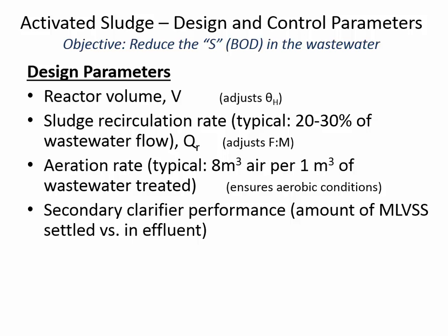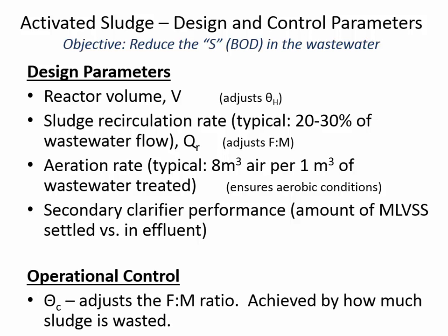One of the things that we have to keep in mind is how good the secondary clarifier is at settling solids. We have to make sure that it's very good, because we want those solids to be re-injected into the aeration basin. If the clarifier downstream of the aerator isn't doing its job, then we won't have the sludge we need to re-inject.